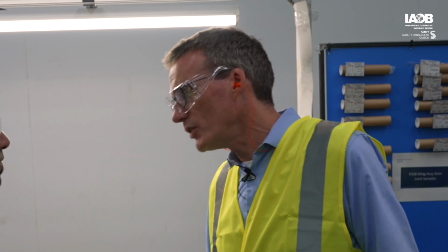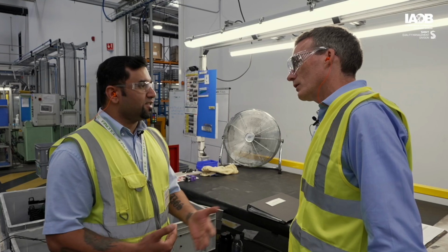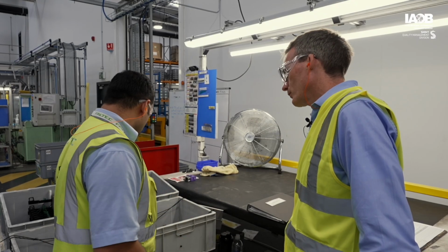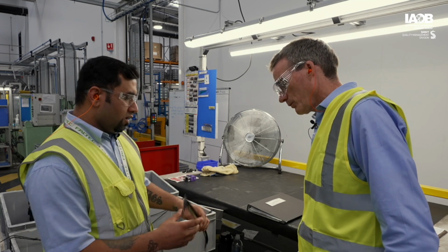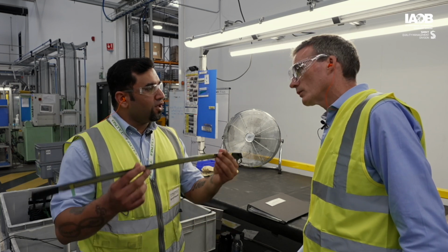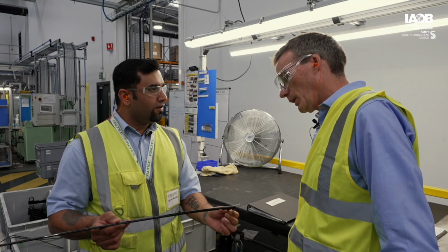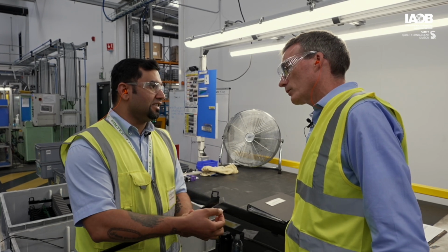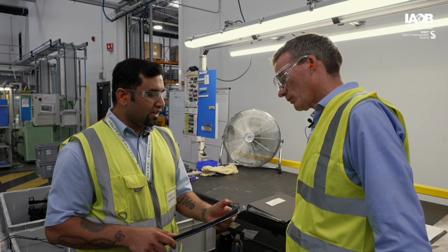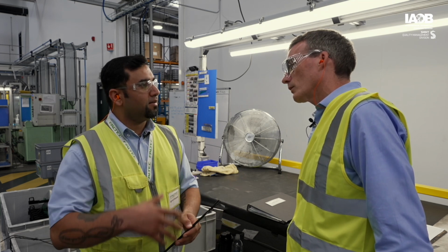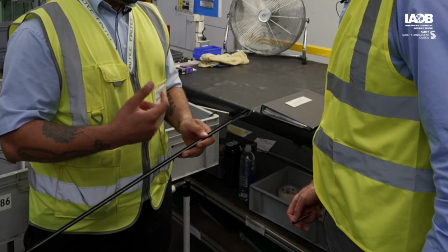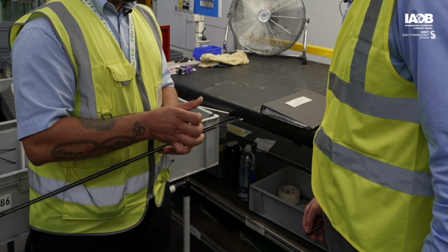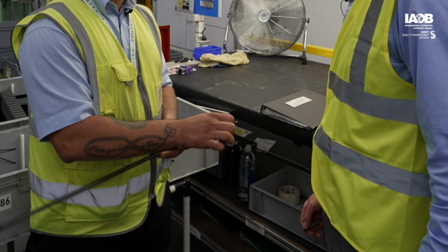Okay. Can you just give an overview of what the problem was that you experienced? From my recent experience, yesterday we had a complaint about this product. Nissan have complained that when they put the part on the vehicle, this end cap comes off. It detaches itself from the part. The end cap is only an adhesive attachment, with a slight adhesive on it. So there is a test implemented by Nissan and Faltec where we push the end cap out, putting a slight force on it.